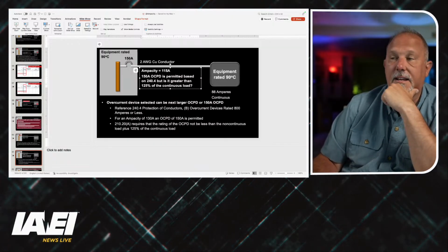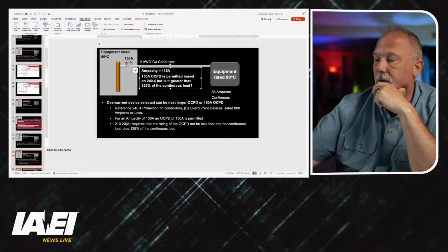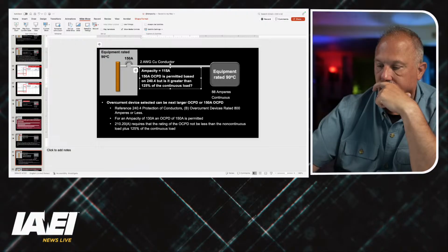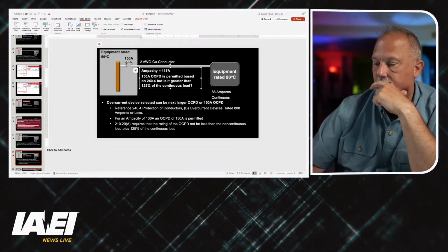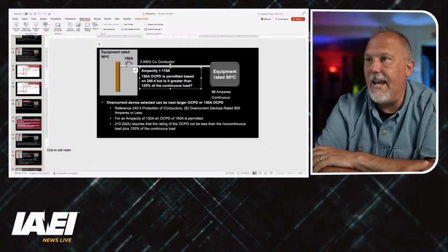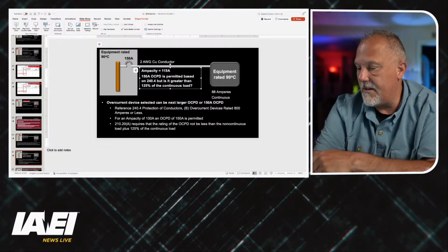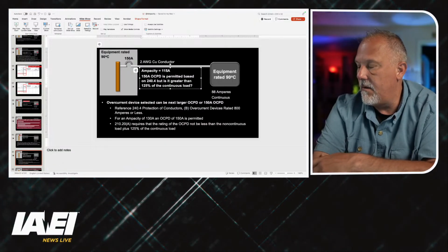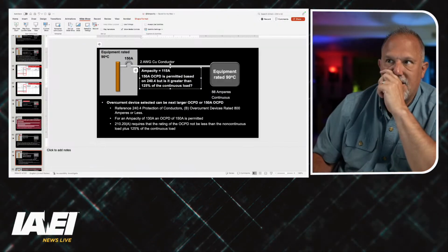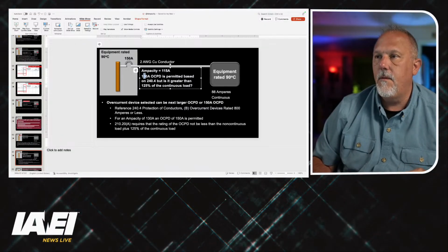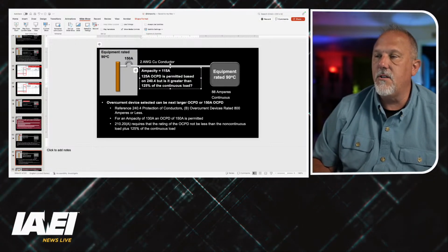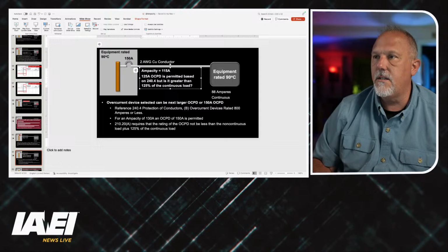So if I have 115 amps, based upon 240.6, I go to the table in 240.6(A), 115. The next higher is 125. So 125 amp. Let's check that. A 125 amp overcurrent device is permitted based on 240.6.